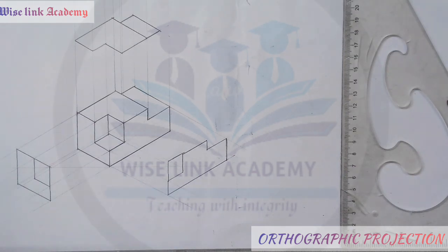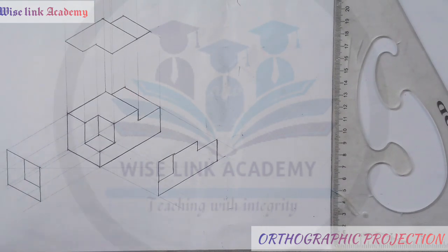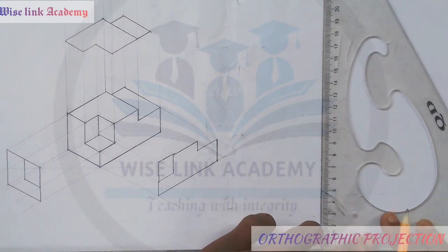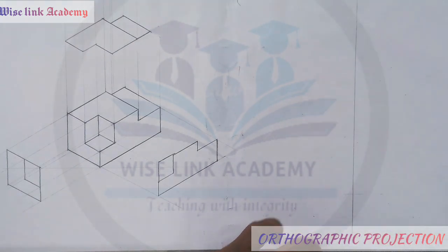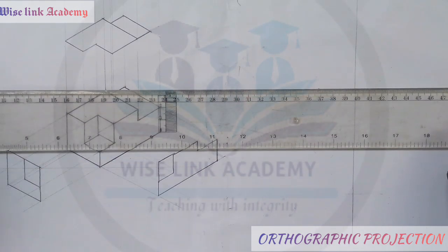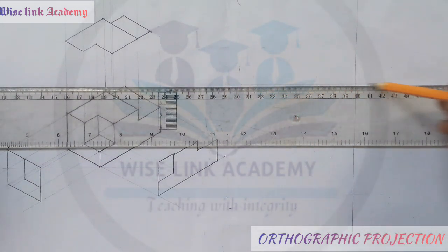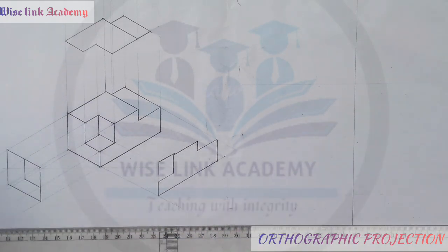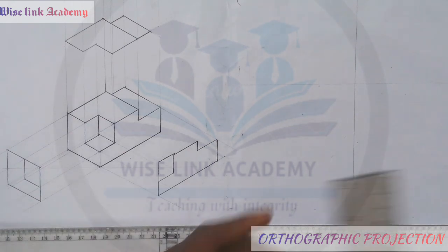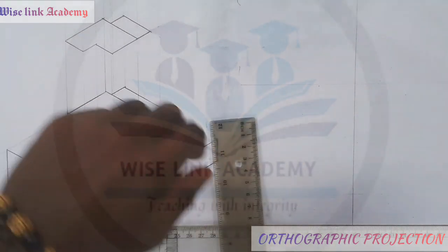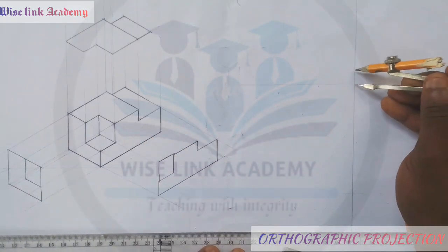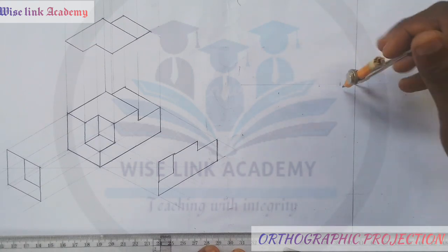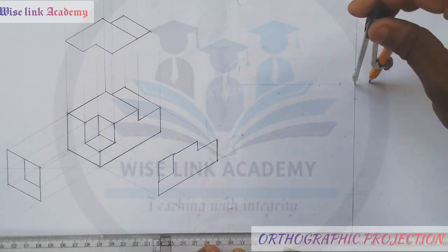Our first task is that to draw any orthographic, you need to draw out your orthographic axis, right? So I'll take my T-square and draw a horizontal line this way. With the help of my meter rule, I'll measure out 10 of a house. With my compass, I'll measure 10 from here to here. It's 10, that's 1 centimeter. Mark up here, mark here, mark down, and mark right this way.